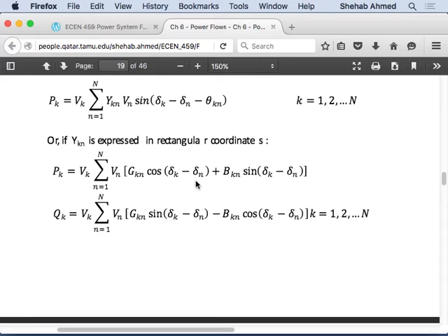Plug it into the system and see what you get. Right? And then in an unstressed system, it may be not too far away. If the system is a stressed system, meaning it's fully loaded, or there's so much reactive power being drawn out that the voltage has dropped considerably, maybe to 0.7 per unit or something like that, or there's a fault somewhere in the system which has dropped the voltage considerably, then your estimate's going to be way off, right?